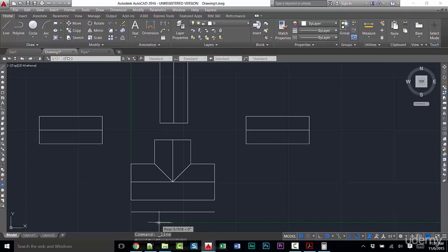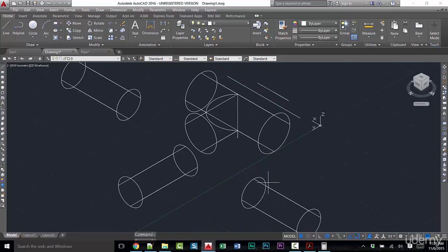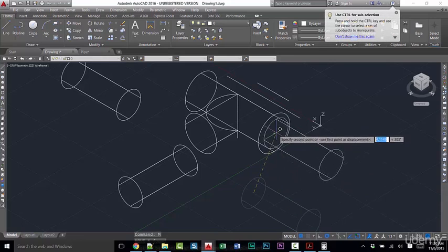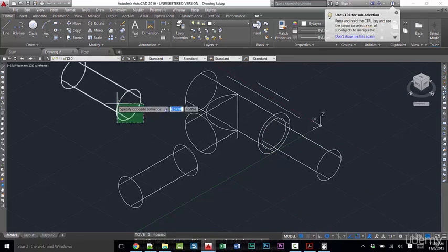0.84375 to the left, and then we can draw another one to the right, 0.84375. So now we've got a line that we can dress to for our 2 socket depths. So let's go ahead and get these 2 end cylinders subtracted out. First, we're going to go back into an isometric view so that we can see what we're working with. And then I'm going to move these cylinders from this center point to the center point of my end tube.